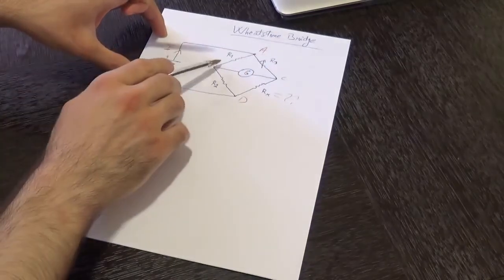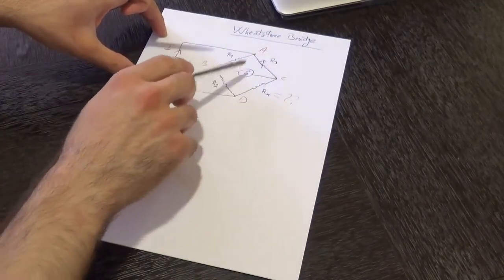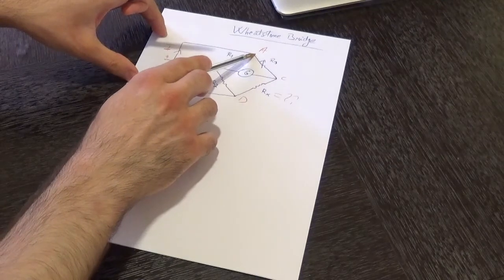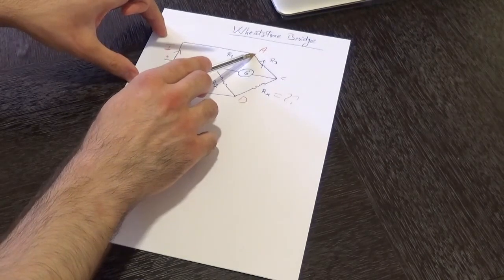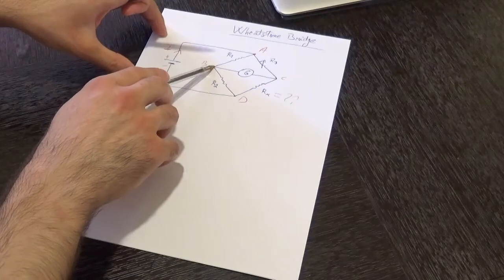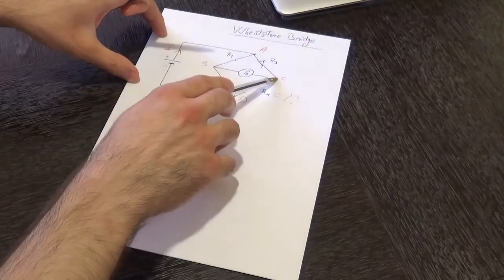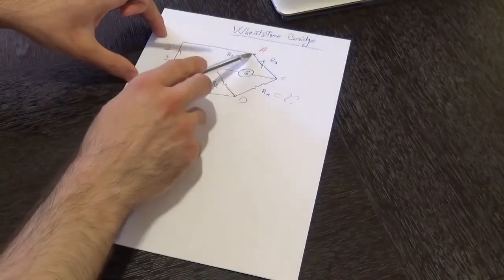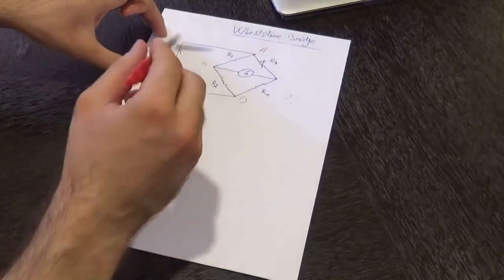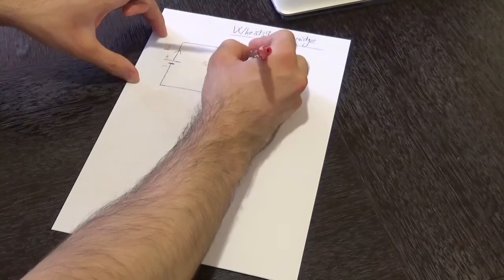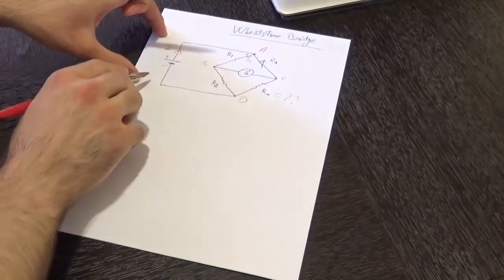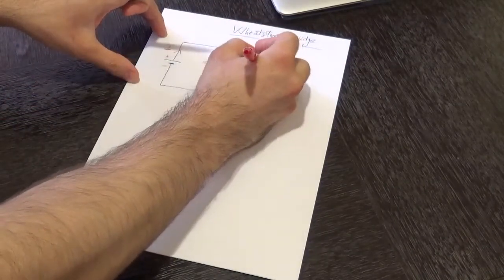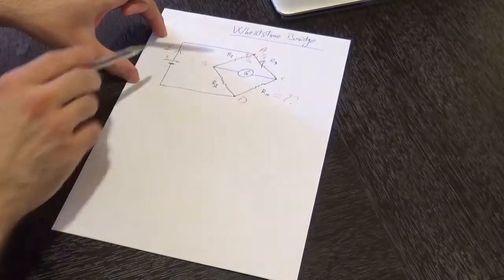So over here we can basically distinguish four different nodes. Node A, where we have an intersection of more than two connecting wires, node B, node C, and finally node D. So that main current I, once it reaches node A, is going to split into two different currents. A current I1, which is flowing through R1, and over here we have current I3 flowing through R3.